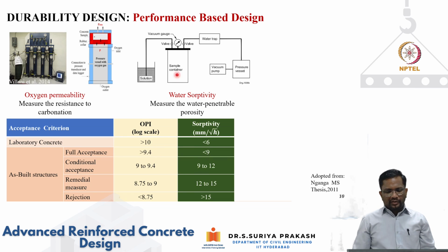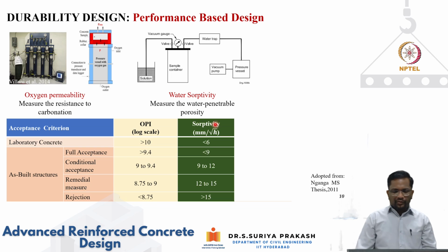Now, the sorptivity test is to measure the water penetrable porosity in the system. And again, you can see we have this kind of a container, and then we have solutions, and then with the vacuum pump, we try to see how much that water is penetrating inside the concrete, and then we measure the sorptivity.